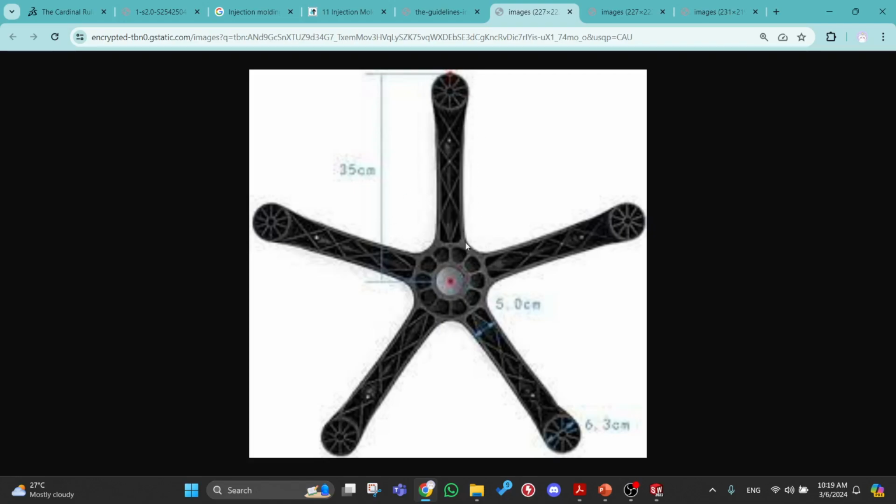It will distribute here, and then here will be a high stress point compared to a single hub, because this part is going to be static. It's like this part is going to be connected to the hydraulic piston, so it's going to absorb all the force there, and here instead it's going to be dispersed out over here. So with a dual hub design, the force distribution is not so nice.